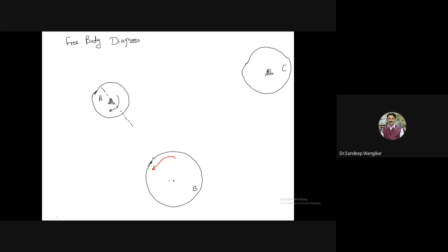So if here this is the point of contact, then PT will be in this direction. It will always be in the direction of rotation. And for this case, it is the opposite direction. So I will say this is the direction for PT. I will say here point number 1 and point number 2. This is between the two cases. Then the PR is always directed toward the center. So this is PR acting on this gear, and this is the PR acting on this gear. And now a similar case I can show on this other side.